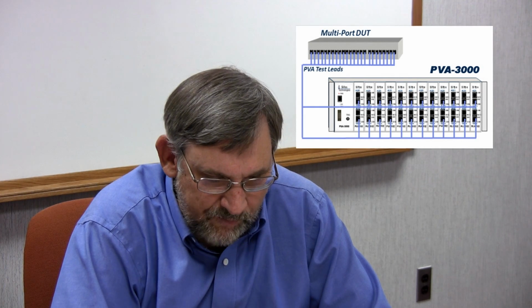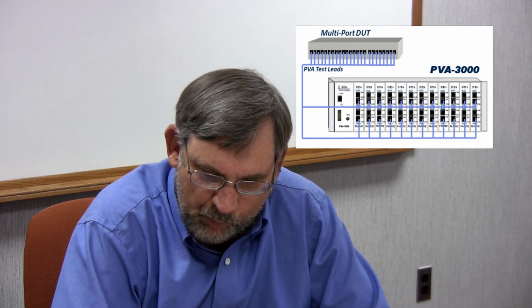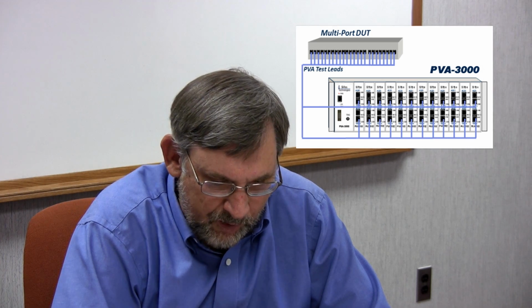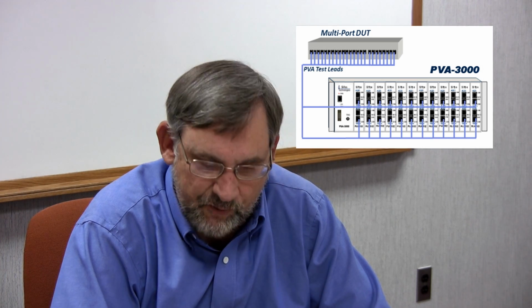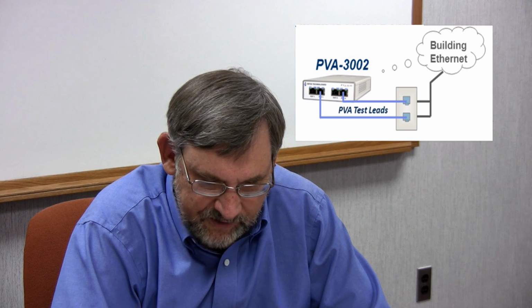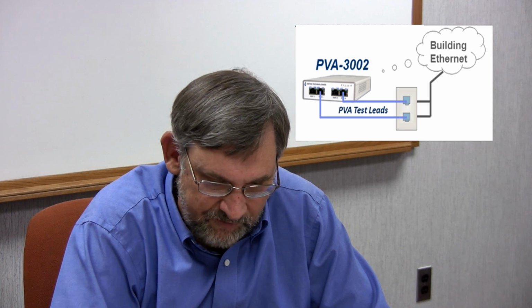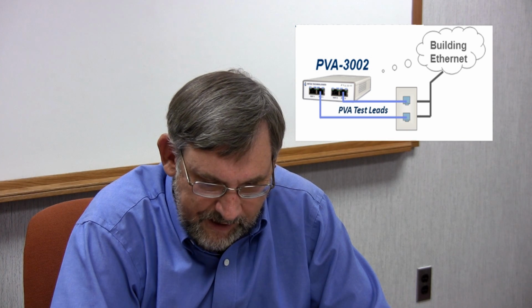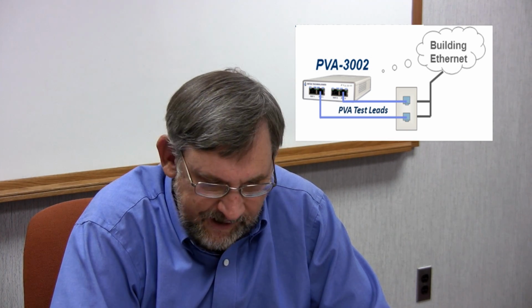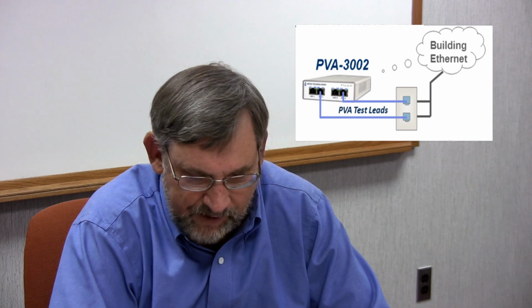Before taking a closer look at the capabilities of the PhyView analyzer, let's briefly review some typical applications and test configurations. Testing a 24-port Ethernet switch is as simple as connecting one test lead, one patch cable, per port between the device under test and the PhyView analyzer. For low port count testing, the compact PhyView analyzer offers 2 test ports and a portable instrument package. The PhyView analyzer can also assess quality of physical layer performance at any service outlet, thereby appraising the combined performance of the Ethernet link partner and the media between the device and the service outlet.